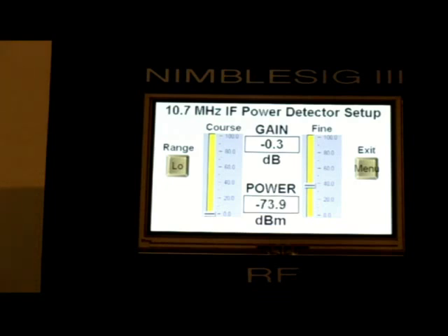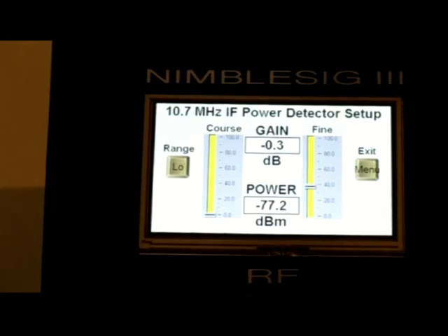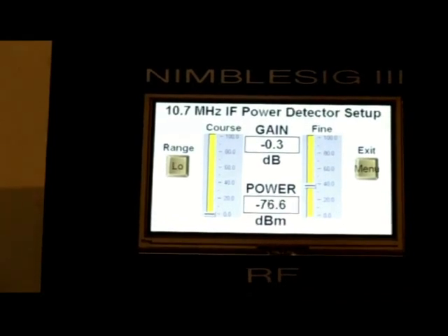The power output of the detector is running at the noise floor at the moment at about minus 77 dBm, which is a typical noise floor for it. And to prove that, I'll just disconnect the input to the IF, and there it's disconnected now, and it's settled down a bit, but still around minus 77. And hook it back up. You can see a little bit of additional noise from the mixer and the IF amplifier and the generator output all combined. Anyway, it's almost as if there's no input signal at all at the moment.